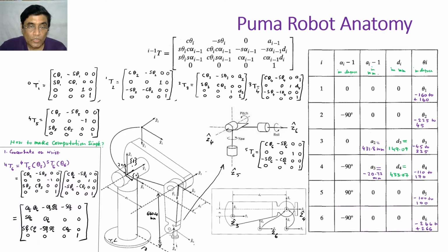Now, another coordinate frame is required. So this is the 0th coordinate frame and first coordinate frame. The 0th coordinate frame is attached to the ground. The first coordinate frame is attached with the robot body. That is, when you twist your body, the motion takes place about the Z1 axis, with respect to the Z0 axis. Z0 is my inertial coordinate frame. You understand, right? So let us put these two coordinate frames together with another coordinate frame here.